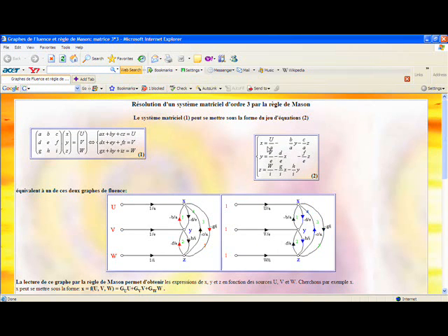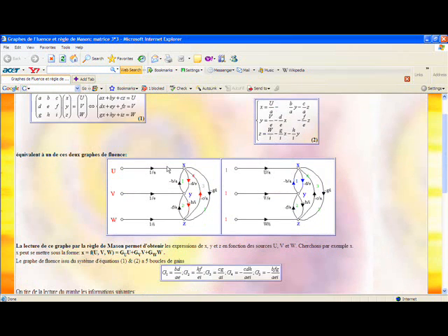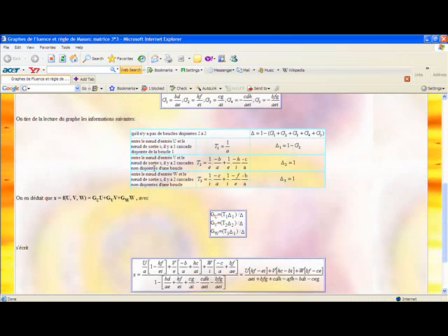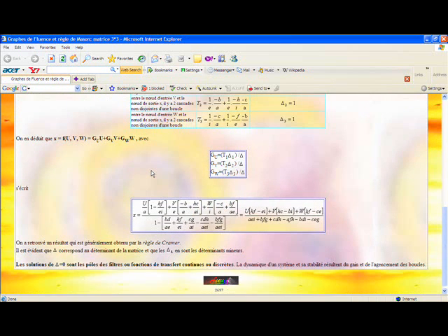technique. As you see here, the matrix is written in the form of equations. These equations can be represented using the signal flow graph method, and using the different techniques we can reduce our signal flow graph, and then using Mason's rule we can obtain the results for our variables x, y, z, etc. Here is the rest of the procedure that shows how to proceed with solving